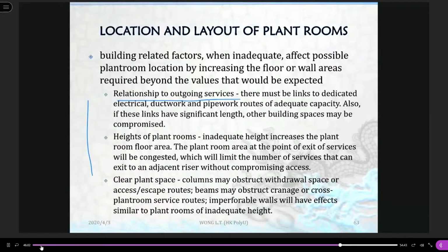Some equipment, such as chillers, may require high voltage supply, or the loading may require more than one transformer to supply the entire plant. So in the special arrangement, the transformer room, the chiller plant, the supply ductwork and the main switch room are related. We need to understand the relationship in order to arrange the plant rooms together, right?